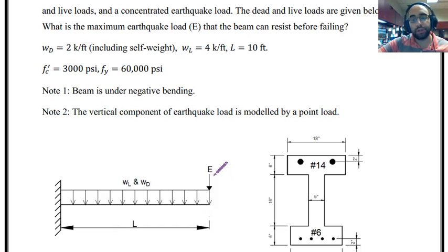Such motions are in general in 6 dimensions, but the typical and common way of showing earthquake load is horizontal movements or horizontal directions, and also in some situations we might need to look at the vertical movement of ground. In general, vertical movement of ground is not important. Mostly the horizontal shaking is the important factor when we study earthquake loads.